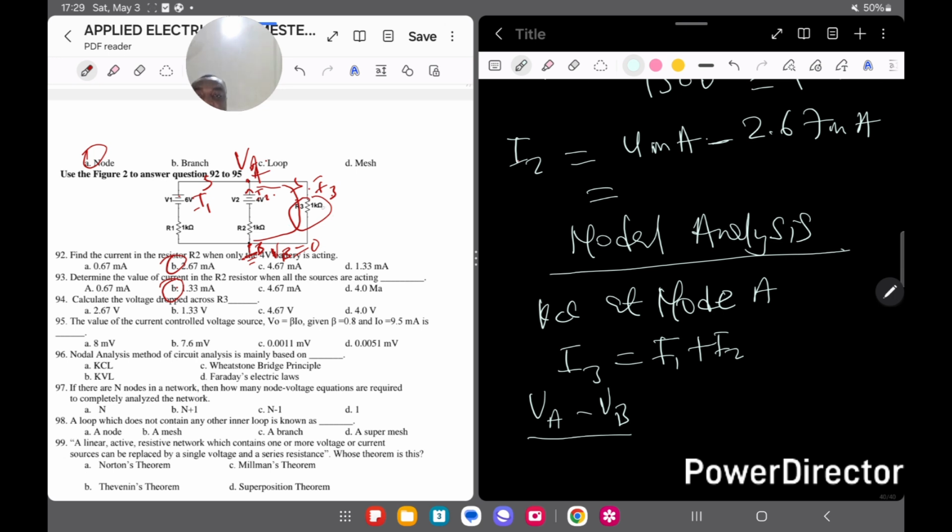We have only one resistor there, which is 1 kilo ohm, and that is 1000. So I'll just take this divided by 1000, which equals I1. Then we go to the first branch. Again, that is the same thing. You can see the current originated from V1, right? And the voltage there is 6 volts. So that's the high potential minus VA because it arrives at VA here.